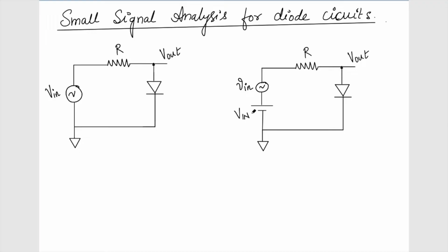In case of the diode, first what we will do is try to find out the DC current only. We have done that. We have solved diode circuits, and there what we did is, given a DC source, what is the DC current, using the constant drop model. Now suppose there's a small voltage riding over it, we will not be able to use the constant drop model, because in the constant drop model the V out is constant at 0.7 volt.